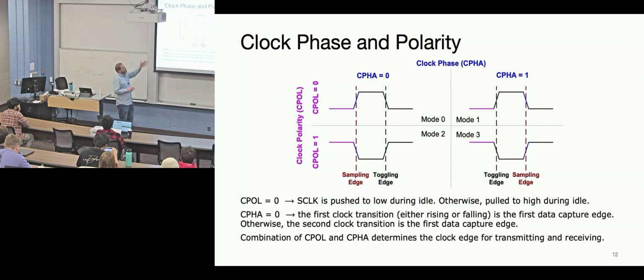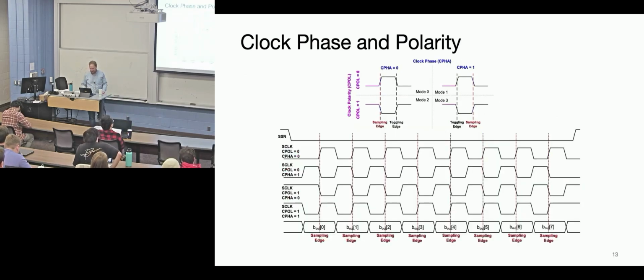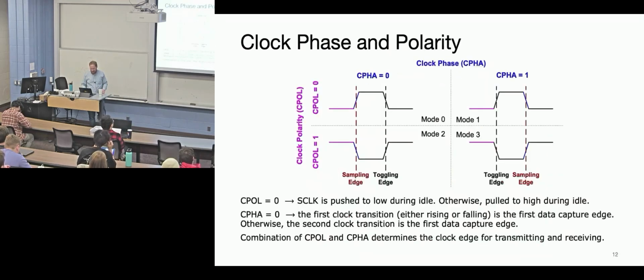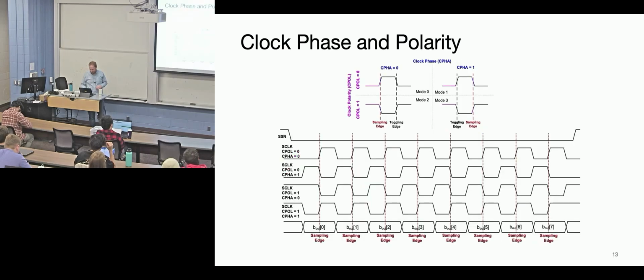And this is where the confusion came up early on. I remember when I was at Intel as an intern, making microcontrollers talk to peripherals, and it was like, oh man, that little, I don't even know what it was at this point, probably a distance sensor or something. Its SPI was only one of these. I think it was like quadrant 1, but my microcontroller only talked 1 and 2. And I was like, oh, I just can't get these 2 things to talk to each other. But now generally you have lots of different options because microcontrollers have gotten more advanced. So to think through some of these clocking strategies, this will show it.